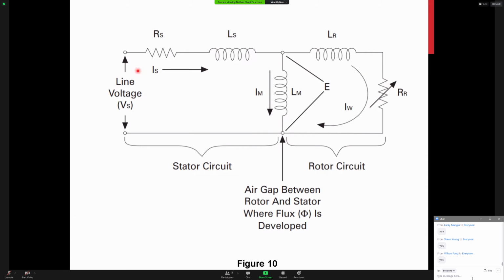So there's two parts to the current that gets drawn. There is the magnetizing current. The magnetizing current is what goes through the inductance of the motor and provides a magnetic link between the stator and the rotor. That magnetic link is what causes rotation of the rotor here. So our stator, of course, has resistance and inductance. So magnetizing current is one part of the current that flows in a motor, and it's generally approximately 30% of the rated full load current of a motor.